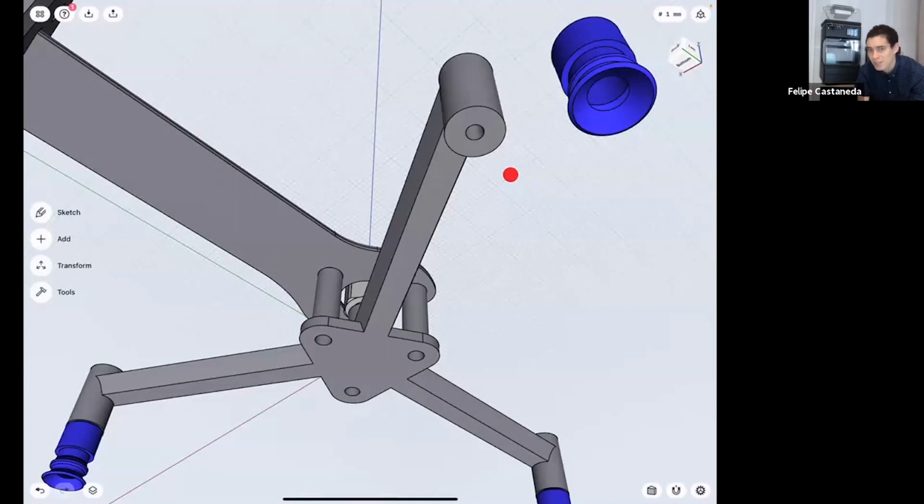Yeah, and that's something I remember from the first couple of times, back in the day when I started modeling in 3D, how easy it was to generate pseudo solids that were not completely closed. If you wanted to print them out, they would have holes in them, or they would simply not print. The slicer would just break because you're trying to export a series of surfaces that in the render might look like a solid, but it's just patches here and there instead of a completely solid body. Absolutely.